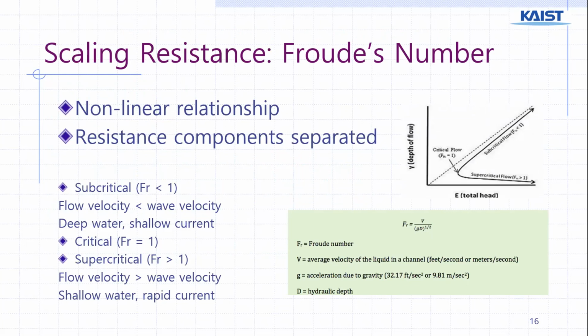So Froude's number is an essential component that has to do with calculating or estimating the resistance. To simplify a really complex idea into a short lecture here, Froude's number basically was revolutionary because it described the scaling of resistance from a small model ship to a larger realistic ship in a non-linear way, and it accounted for it in an effective manner.